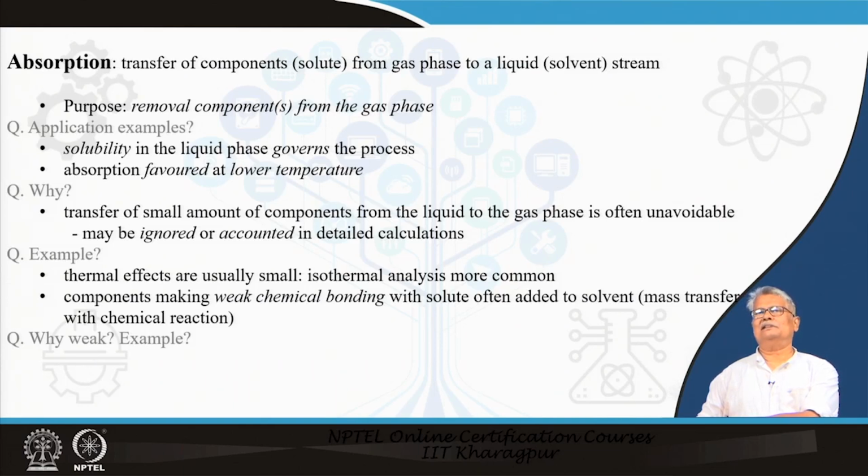And in fact, what happens is it increases the capacity of the solvent to absorb more and more amount of ammonia. This is quite often the process, and you often have cases where we add chemicals to improve the capacity, the effective solubility of the solvent, which forms a weak chemical bonding. Here I have got a question: why weak chemical bonding?